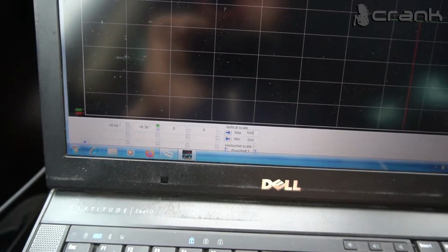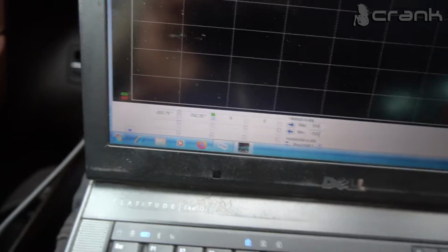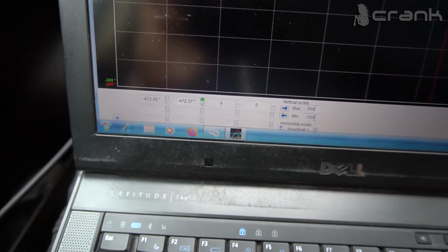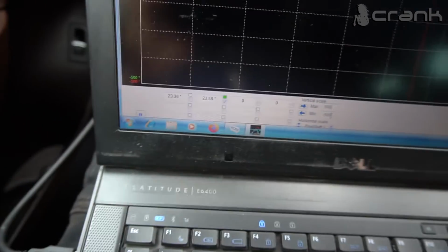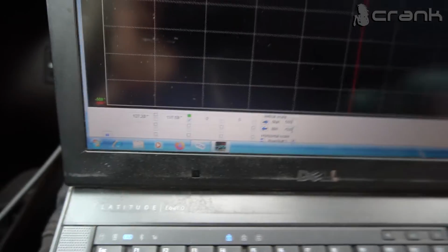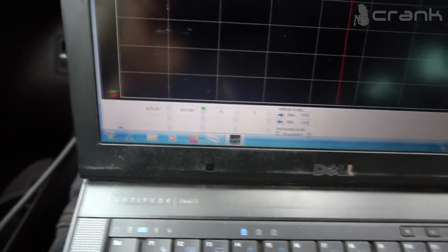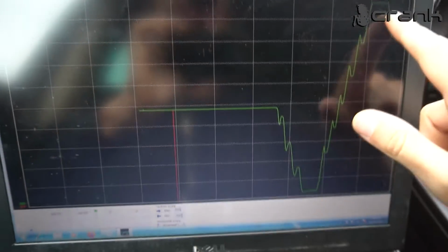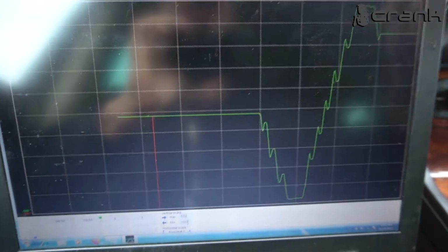You need to set it to 500 because, let me show you, when we rotate the wheel, how much are we going to go? Minus 480, and if we go on the opposite side, we're going to be somewhere around plus 480. So yeah, 477. So as we can see, this is the exact movement of the wheel which we are seeing.